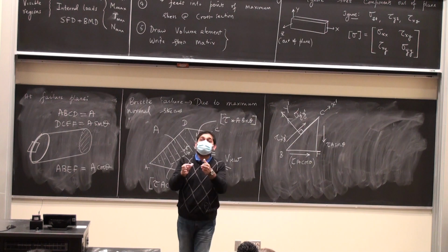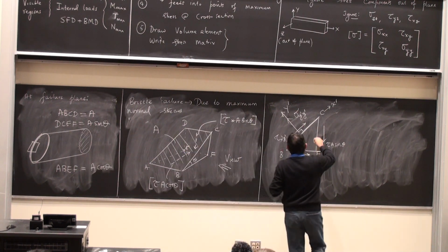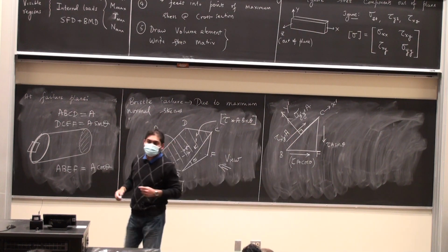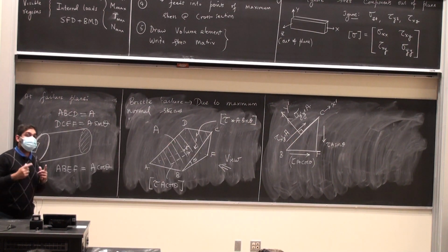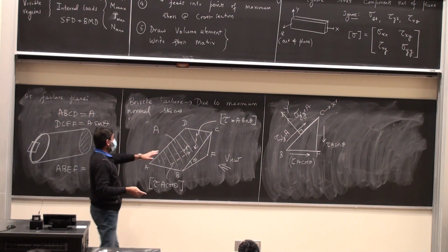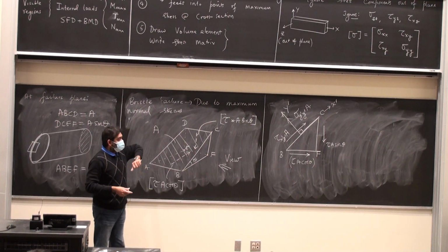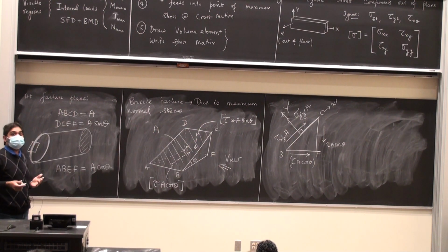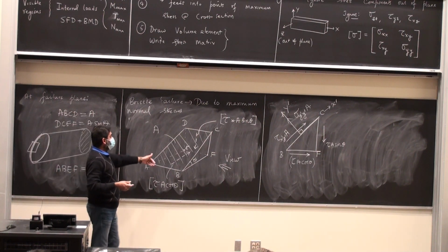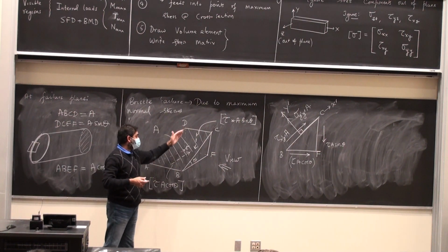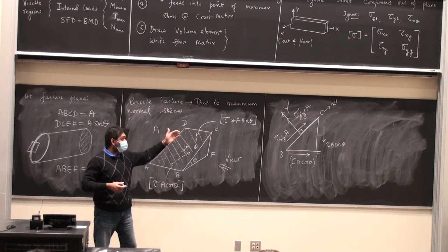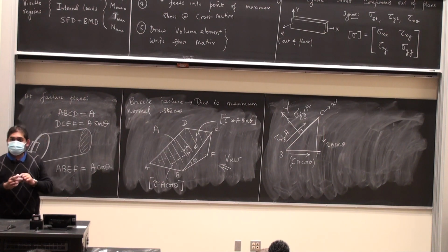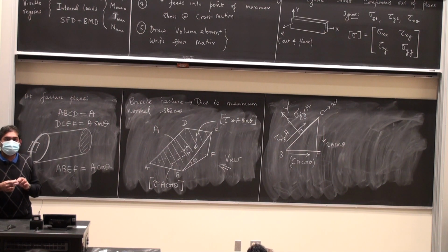If I multiply it by the area, these stresses become forces. What is the area of the shaded face? Capital A. I'm drawing forces, I'm not drawing stresses. This is the figure that had the forces here. From the volume element, I multiply it by the area of these faces, I get a force rather than a stress. I do the same thing. On this total surface area A, I have stresses which are along the incline and perpendicular to the incline. Multiplied by the area, they become forces. All of you with me so far? Okay.